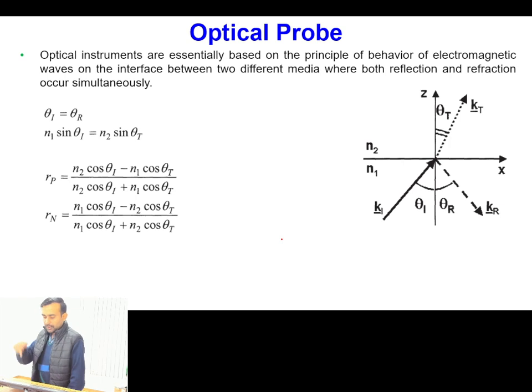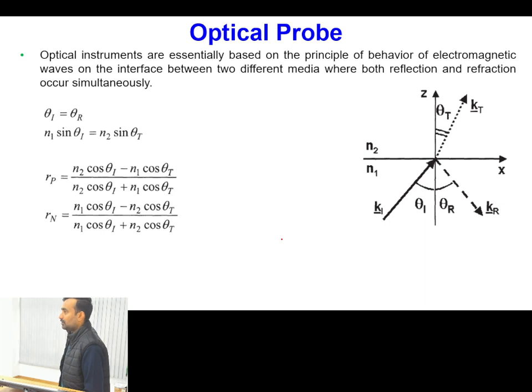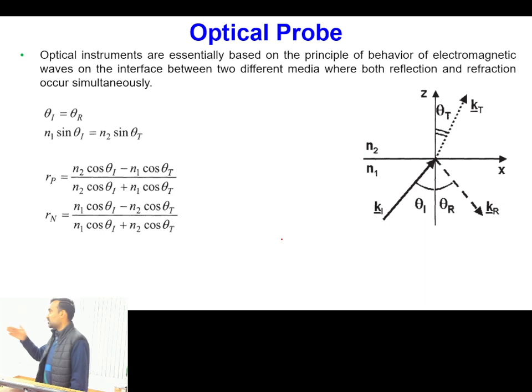If I am putting the probe within the pipe, then the material of the probe should be transparent. And if I am using the probe from outside, then the pipe material should be transparent, because we are now dealing with optical signals, which need a material transparent to light. Is this point clear?